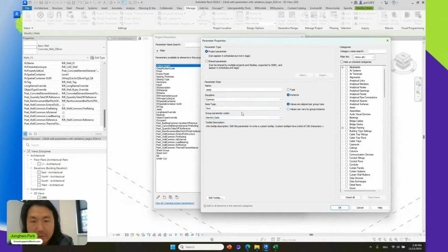So all this process, we did it with the Rhino.Inside Revit components. And also the data type between type or instance or global parameter, we already define it here. And also which category you want to provide. So this was already all automated from our Excel file as a data input.